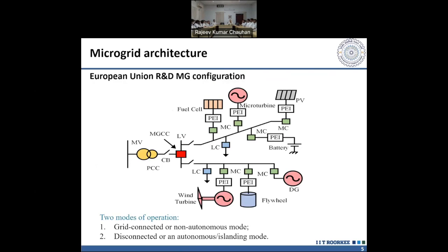So that's why normally, in place of going to the transmission side, we try to integrate it on the distribution network, which is at low voltage, because the voltage they are developing is not of a very high value. Otherwise, to convert this again, you require a very large transformer to integrate it with, say, 132 kV.